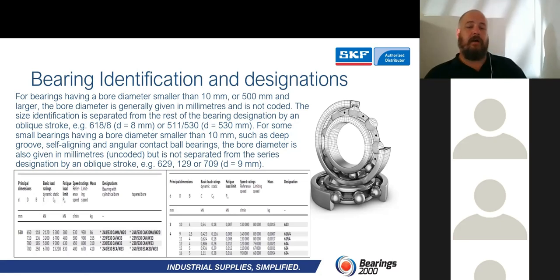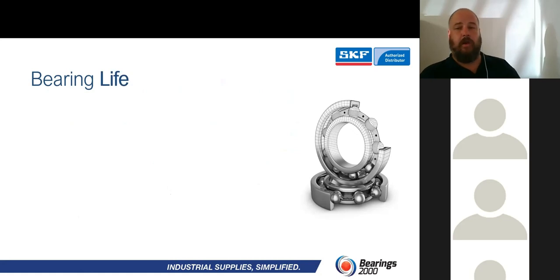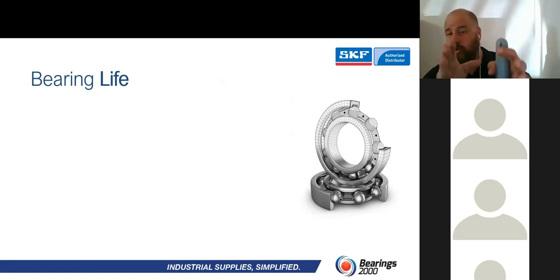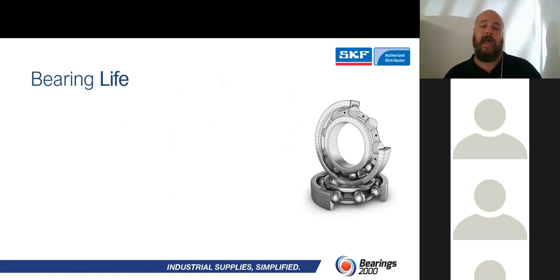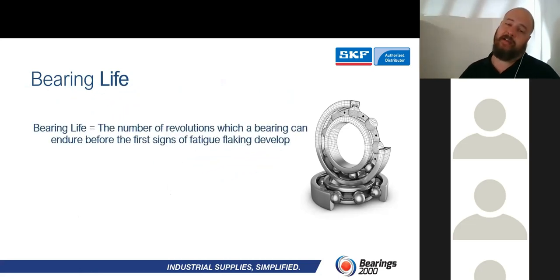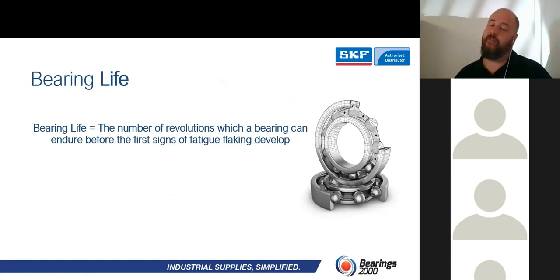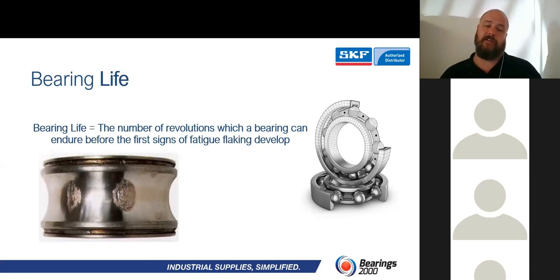Okay, so now when selecting a bearing, we've got to understand that a bearing only has a certain lifetime. A lot of people would say, yes, the bearing is guaranteed for life. It's not my life, it's not your life, it is in fact the life of the bearing itself. Bearing life can be simply identified by the number of revolutions which a bearing can endure before the first signs of fatigue, flaking, develop. There's a nice little picture over there. That is just fatigue, guys.